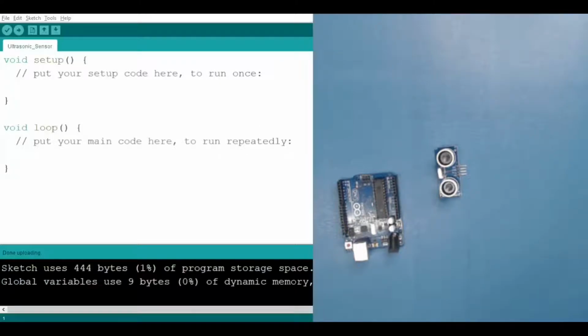and let's turn on the Arduino. Now in the Arduino, what we are going to do is install a library. For installing the library, go to Sketch, and in Sketch go to the Include Library section, and from Include Library go to Manage Libraries. When you click on that, after some time you will see a pop-up window appear. So let me show you.